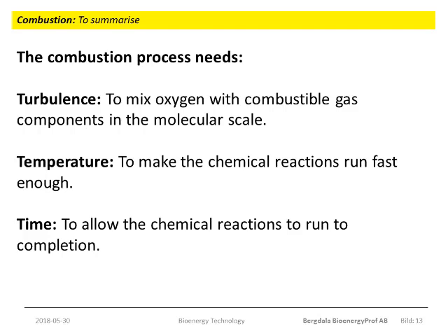So once the microscale, molecular scale mixing is finished, and supposing the reactants have a proper temperature, then you only have to wait and the reactions are likely to occur. Therefore, the common saying is that combustion depends on 3 T's: time, temperature, and turbulence.